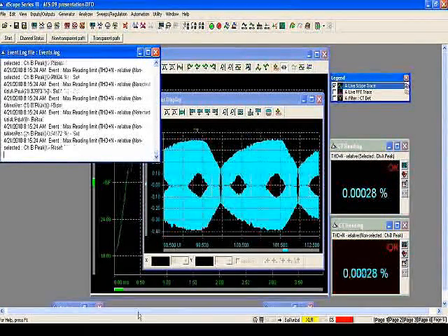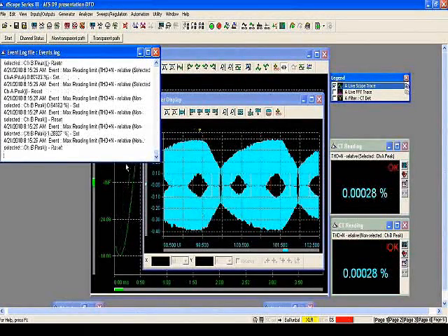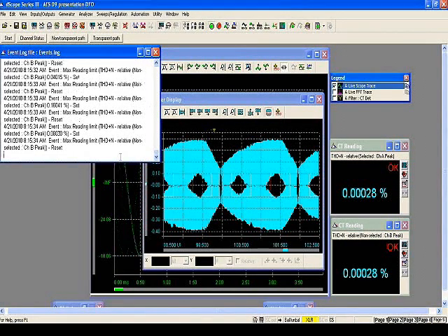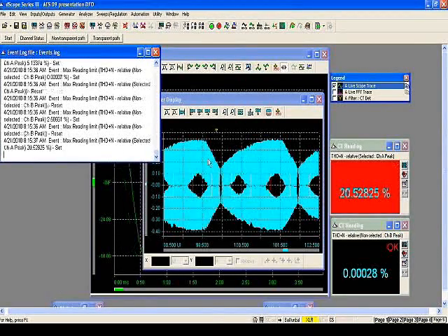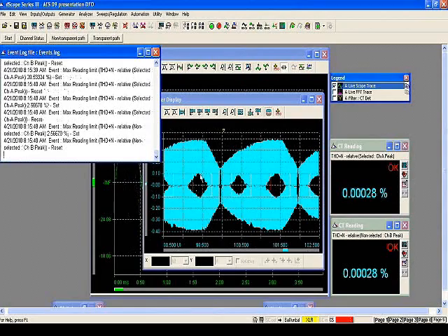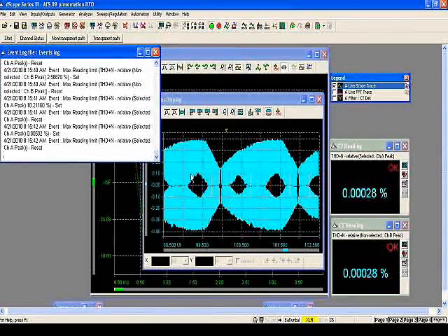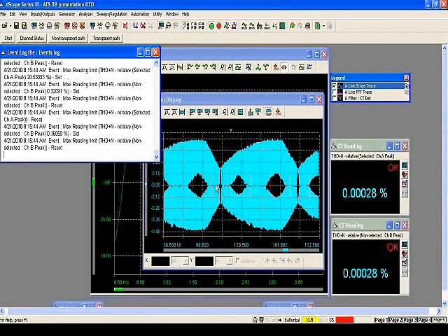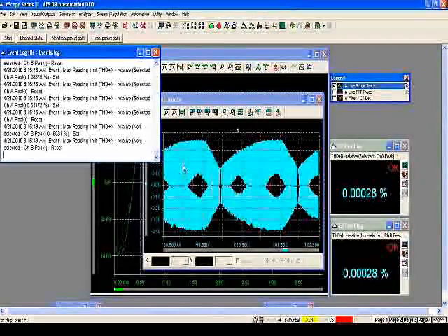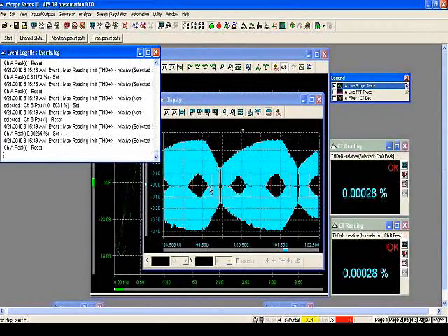Now, this can help considerably, because typically this is possibly done or manifested itself because there's some kind of electrical disturbance possibly, or something's being switched in the router at a particular point in time. But in the case of electrical interference, this eye pattern that we're looking at is the data stream. These should be all square edges. Obviously, that's not the case.